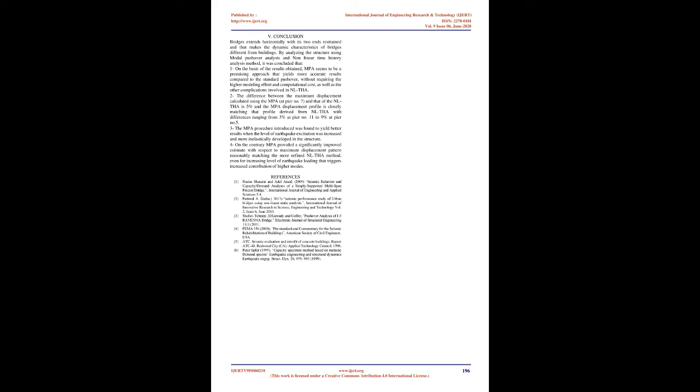The MPA procedure, which accounts for 4 transverse modes, predicts well the deck displacements of the bridge. Moreover, the MPA procedure is much closer to NLDHA and gave better predictions at the end areas of the bridge as the level of excitation increases and higher mode contributions become more significant. Fig. 4 Deck displacement at the pier location.